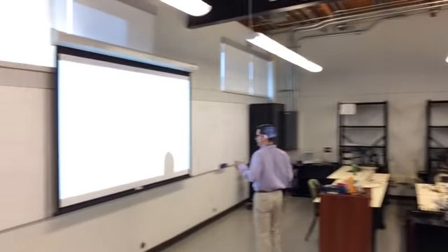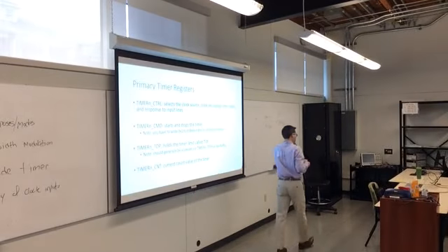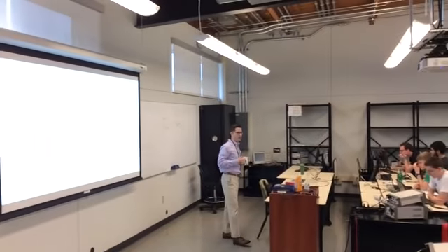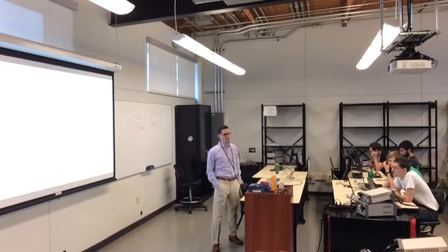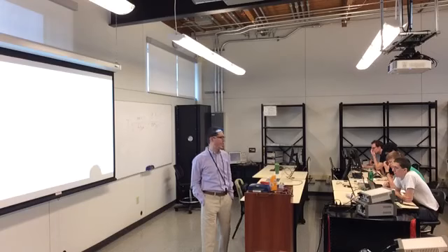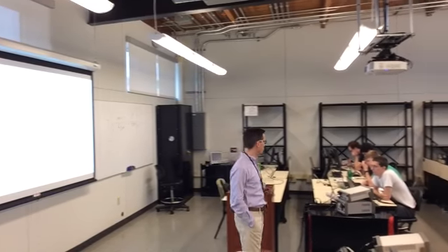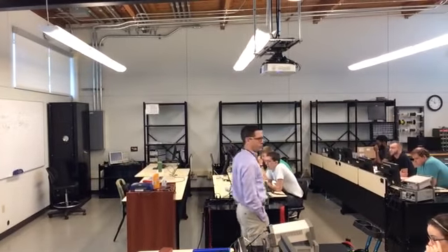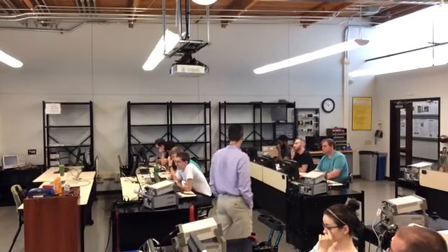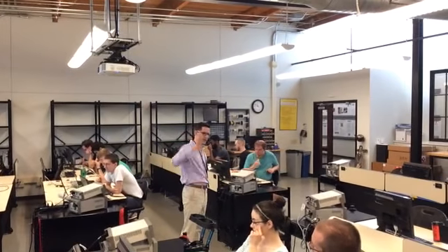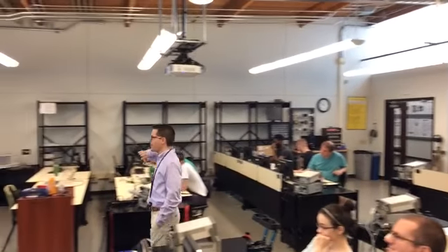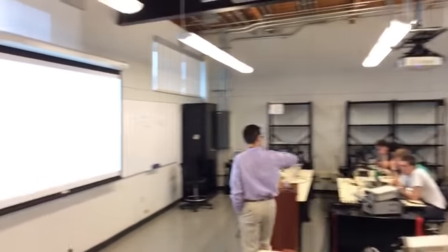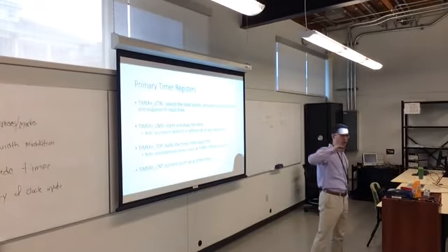Top holds the top value in the timer. One important note is that there is a buffer register for the top value, because since top is being actively read and used in hardware, you don't want to write to it directly because you could cause a glitch. So there is a buffer register that if you write to first, it'll automatically copy into top. You will see that on a variety of peripherals, especially on the UART, which is a communication system.